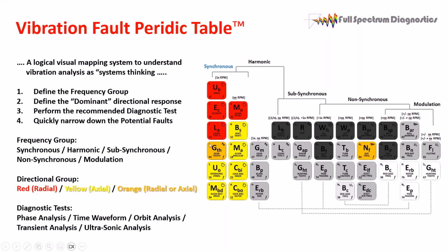One of the things that can happen is we can take our camera out there, which is our cell phone, and put it on a tripod, take about 15 seconds of data, and analyze that. And we'll see if there's any motion that we can see in the 2 planes that we're going to be testing. Remember, it's a two-dimensional camera trying to take video of a three-dimensional machine.